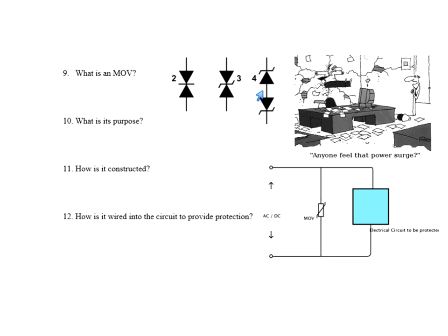But what is its purpose? The purpose of the MOV is to protect against voltage surges. It's always placed in parallel with the load, like a Zener is. This load might need only 120 volts, and if you were to be in a lightning storm, the purpose of this MOV is to shunt any kind of high voltage spikes coming in the line that could possibly damage this load. So it's placed in parallel, so if I get a lightning strike, all that energy gets shunted through the MOV to common before it gets to the load over here.